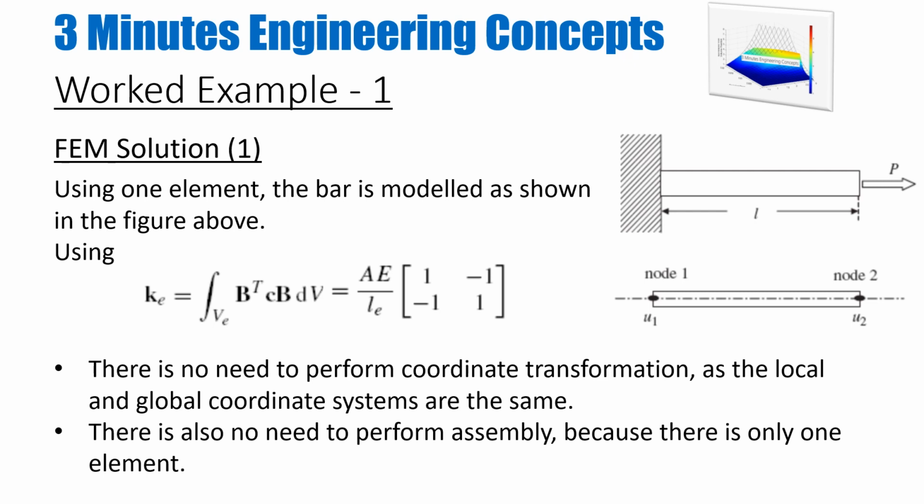to show you how you can use those FEM based equations which I gave you in the previous videos, and I have been repeating them many times, how I can use those to find out the same things using FEM equations. So the only difference in these cases is I need to first start with my stiffness matrices. So my elemental stiffness matrix, as you remember, was B transpose times the E matrix times B times the volume. And I give you the relationship based on my shape functions, which was this.